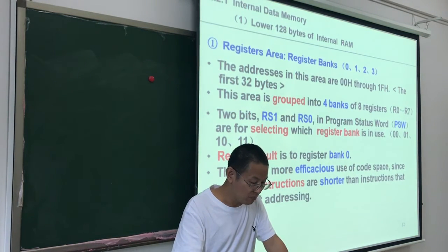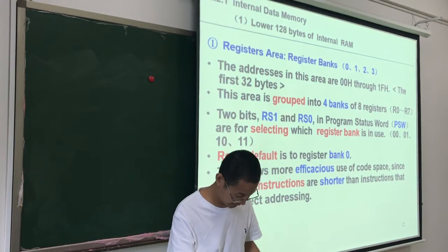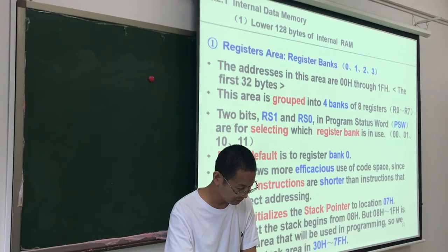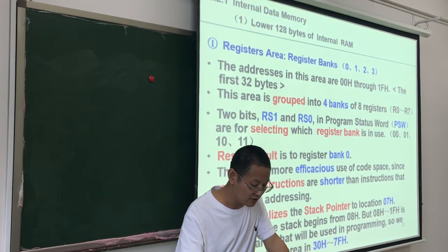This enables more efficient use of code space, since register instructions are short, compared to instructions that use direct addressing. Reset initializes the stack pointer to location 07H.